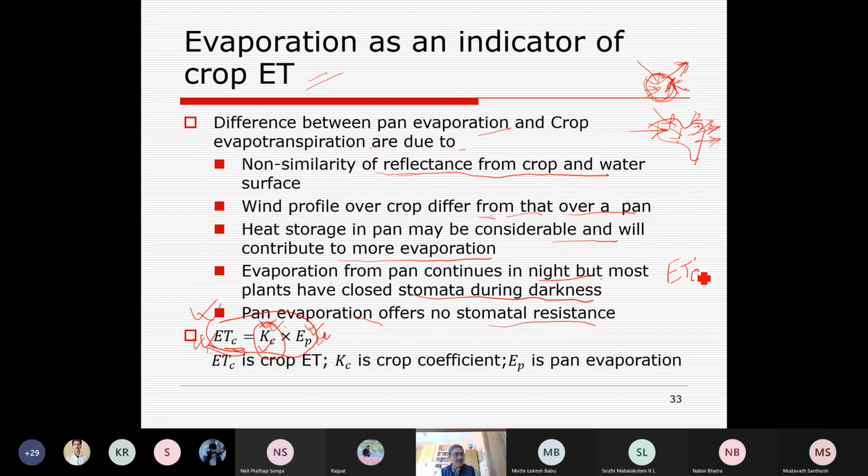Now the third. Lysimeter was a field instrument, those were the measurement aspects. That was pan evaporation, or evaporation based estimation. So this is the pan based evaporation kind of measurement. Solar energy that is coming, here you can see, calories per square centimeter per minute. That is a kind of solar constant above the atmosphere. Above the Earth's surface we have the atmosphere. So above the atmosphere it is calorie per minute per square centimeter. It is coming. That is solar.